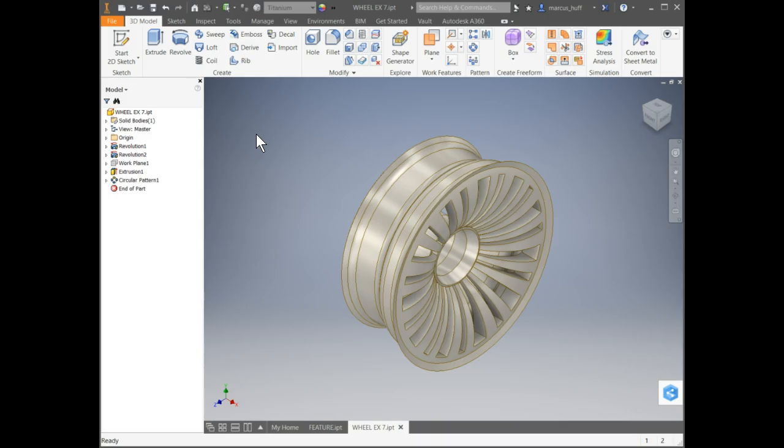One of the things that will happen to you a lot in Inventor is you think you will be doing something and your left click and your command won't seem to be working. Something you need to keep in mind is our motto when we're using Inventor: keep calm and press escape. That usually will make things start working again. Sometimes you'll turn on a command inadvertently, and it puts it in a state where it's waiting for something specific to happen, but you don't know what it is because you did it by accident. All you have to do is escape a couple of times, and it will turn that off.